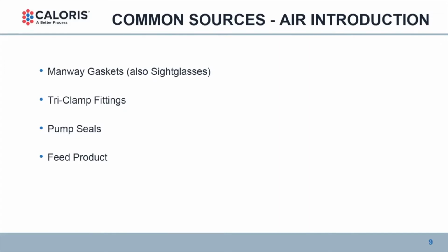Dissolved air, dissolved non-condensable gases, carbon dioxide, any number of non-condensable gases can be introduced into your system with the feed. And that's an inevitable aspect of evaporators that we need to take into account and design features to remove that non-condensable gas that's coming into the system.